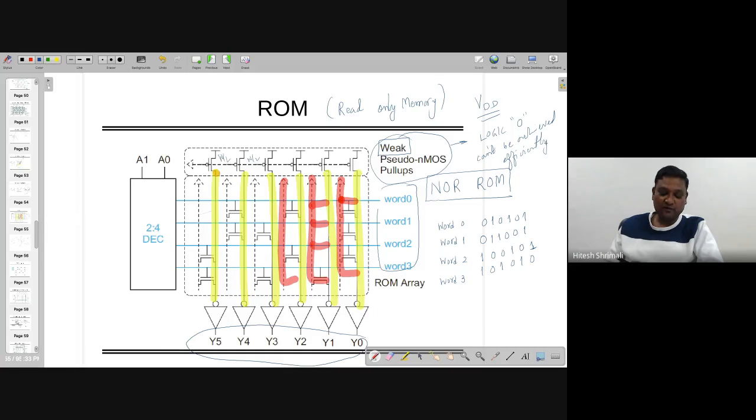Even if it's in micro or millivolt, it's okay, fine, like 1 or 2 millivolt. But if it is going to 200 or 300 millivolt in a 1.2 volt technology, it's quite a big thing, right? So if it is touching the noise margin low, then of course it creates a problem for you. So in that case, it's better to avoid it by taking the weak pseudo NMOS pull-up, right? This theory is already known to us, and we already studied it while understanding combinational logic, right? And this was also a question in quiz 1, what problem will be associated with a pseudo NMOS network, right?